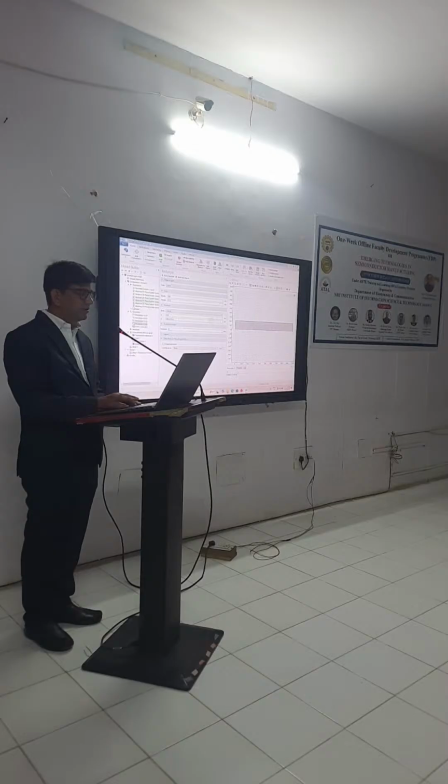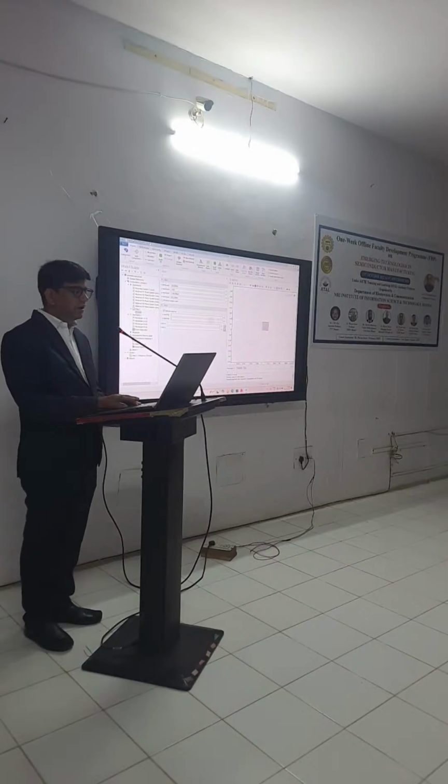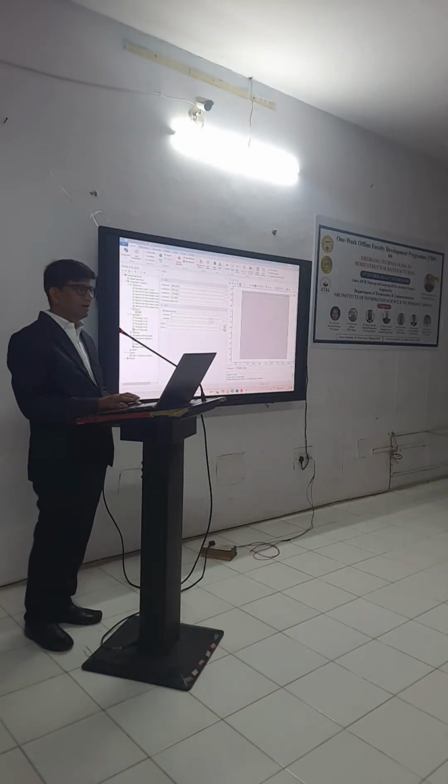Once we go into geometry, and go to view, axis, and once we click here, I click on this preserve aspect ratio, so it looks like something we can easily visualize, our device.